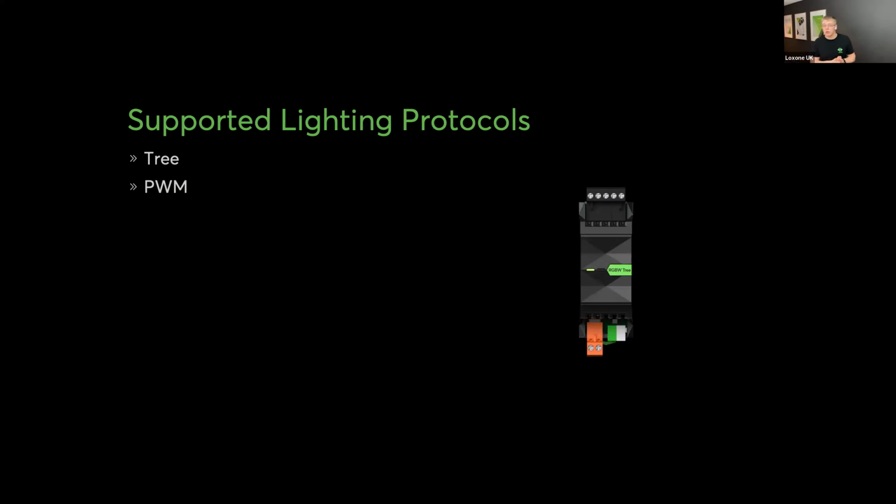So we can then move on to PWM. Now, PWM has such a massive potential behind it, because this is how, I won't say all, but most extra low voltage 12 or 24 volt lighting and all LED lighting is dimmed. Because if you have an LED, your LED isn't going to be running at 230 volts. In your individual light fittings that you're buying from Screwfix or your local wholesaler, they will have a small transformer built in, and the physical LED is receiving 12 or 24 volts.